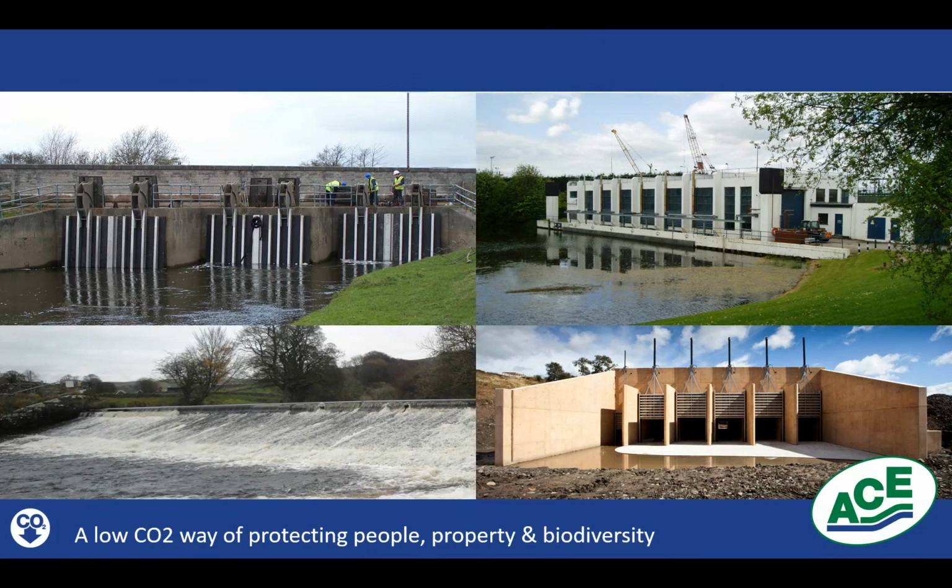We've got flood storage systems such as Morpeth, which is in the bottom right. So at Morpeth, we delivered the penstocks, well, the full M&E package actually. So penstocks, hydraulics, HPUs, control panel, everything mechanical, electrical on that one. But that is in a sense a flood storage dam. So when the water passing downstream increases above 100 cubic meters per second, the dam starts to close systematically. That protects the town of Morpeth downstream because they can't fit more than 100 cubic meters per second down the river, and creates a temporary reservoir upstream.